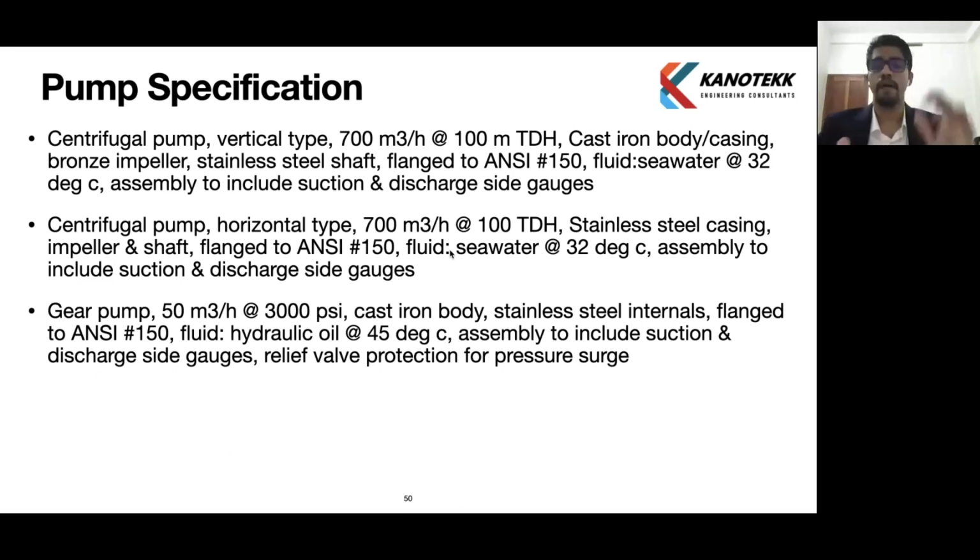In other terms, for oil systems we generally prefer gear pumps, etc. But because of the high flow rate, we use centrifugal pumps in marine vessels, offshore applications, oil and gas applications, refineries, etc. So that is about pump specification.